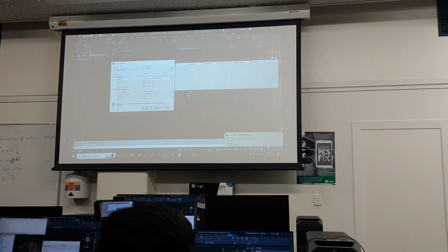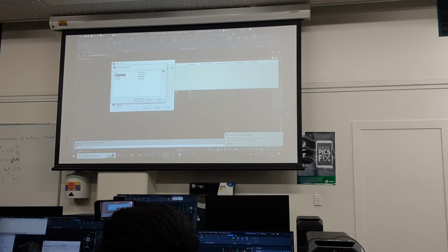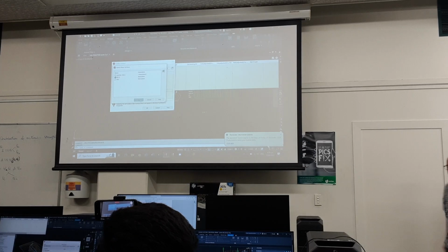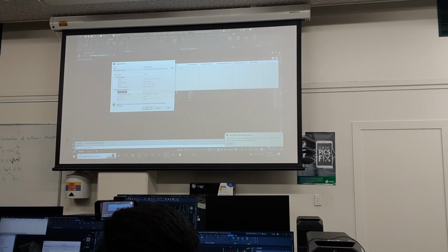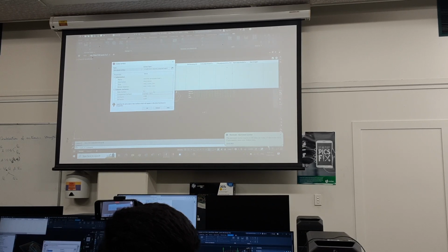Oh, hold on. Choose your base surface. The base surface, if I click on that, there's little dots on the side. Choose your existing, and I'll go to EG1. Yep, and okay. And the comparison surface, the next one down, is the corridor. Yeah. This is why we label things nicely. So as you can see, I labelled my corridor 20, and I labelled my base surface EG1. So if I'm lucky, I've chosen the right ones, and I can now go OK,